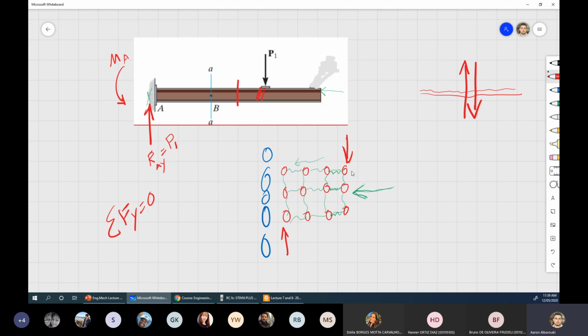To a certain stage, it will stay as a spring and will go back to normal. But if I go past that elastic point, that will create a permanent deformation. I wouldn't call it damage yet. Permanent deformation. That's the yielding point. It's the point where the force you applied was stronger than the material. You made the material yield. You won, or the force won, the material lost. That's the yielding point. That means these springs stretched too much, so they can't go back to normal.